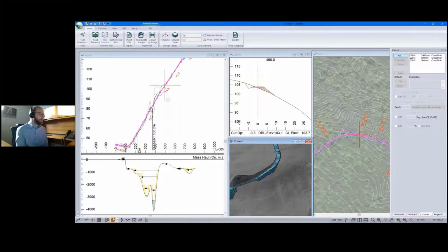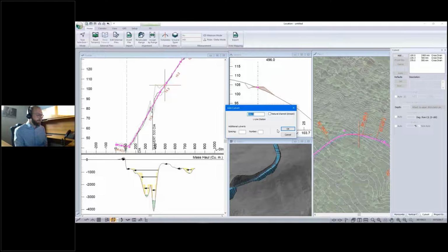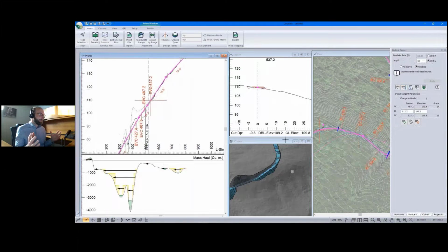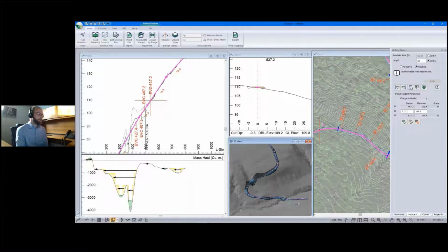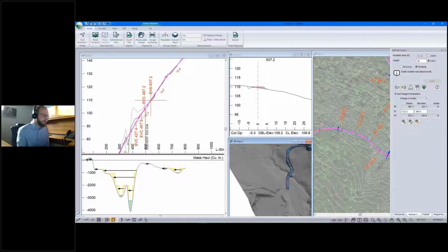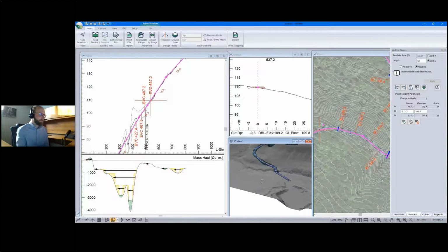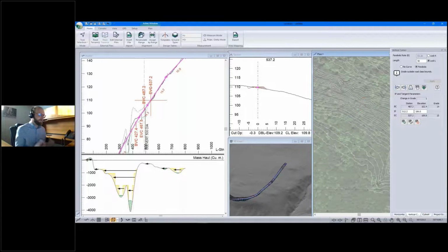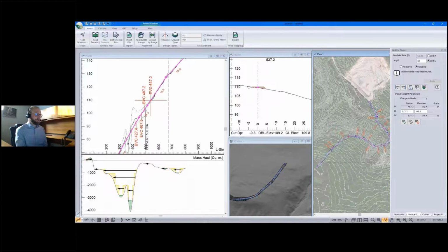We'll also want to add cross drains anywhere we have a low point where water is going to pool against our road. And more so if that water could pool against the road and overtop the road if we had enough water. So that'll wash out your road. But then if we have long segments in between those culverts, we still want to add more pipes than just that. And that is we're intercepting the flow from those cut slopes outside of the actual drainage paths. And we don't want to accumulate so much flow there that we concentrate it, it builds up energy and causes us erosion issues in our ditch or wherever we discharge it.